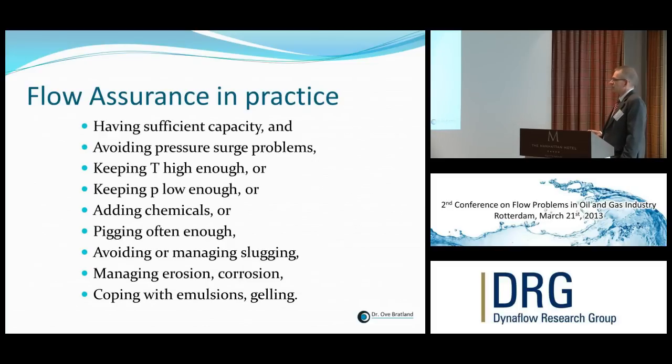Also, avoiding pressure surge problems we have heard about. How do we avoid high pressures that can damage our system? That is mostly a problem in single-phase liquid flow. It's not so much of a problem in multi-phase flow, believe it or not. You might think when you have slugs and everything moving around there, then it would create big pressures and maybe destroy our pipes. But that's not the main problem because it's relatively soft. You have many bubbles in there also, so it's not so hard pressures, you might say, coming out of it.